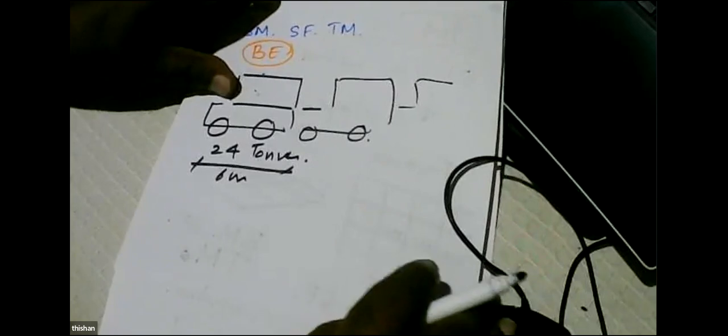And then when you look at the effect of this, you have a lane which can vary from about 2.3 meters up to 4.8 meters. So generally, this is a variable parameter. So for a lane which is about 3.5 meters, they found that this load can be about 30 kilonewtons per meter per lane, giving an intensity of about 8.5 kilonewtons per meter squared.